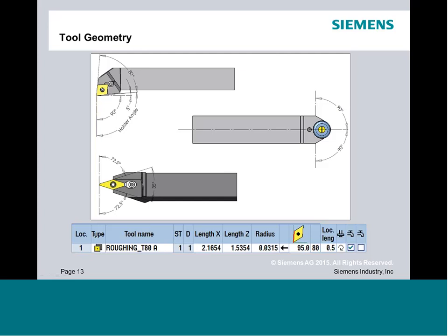Now the reason we're coming off that base position is that if you look at a simple neutral tool, we're still coming off the same base, but now the value for orienting that insert is actually less than 90. So here I would physically put in 72.5 degrees. Now when you get to button tools, they are a full profiling tool. So here we don't ask you to give us that relief angle because we expect it to be a full 90 degrees.